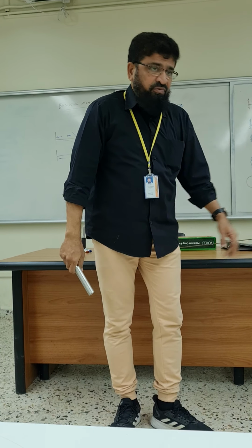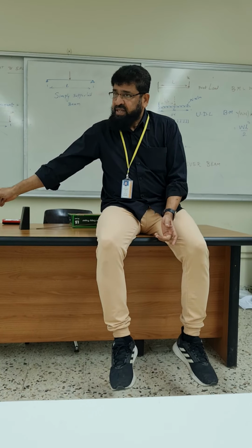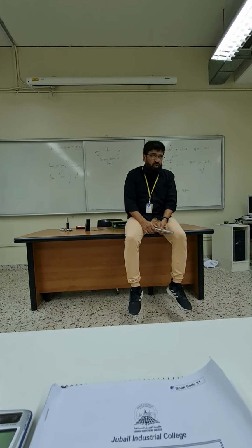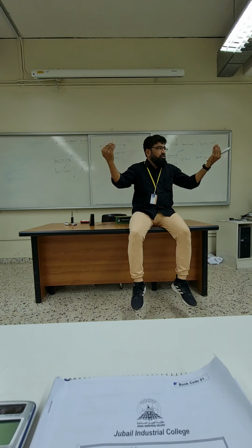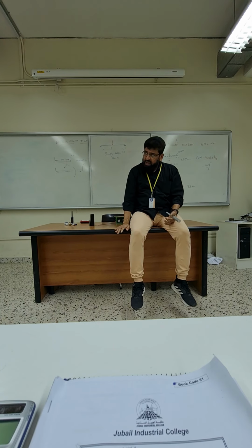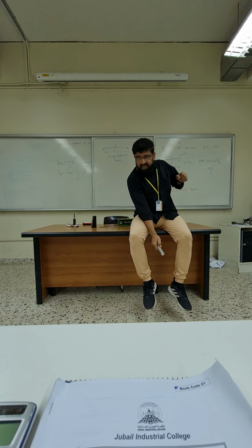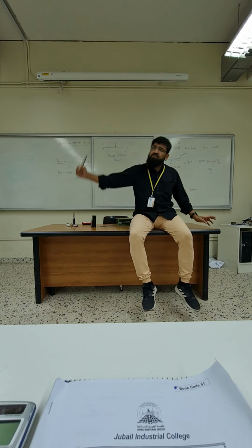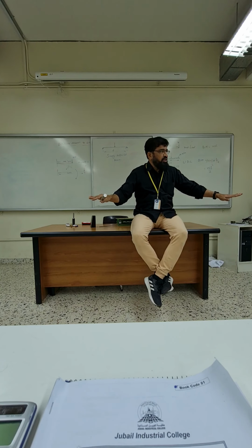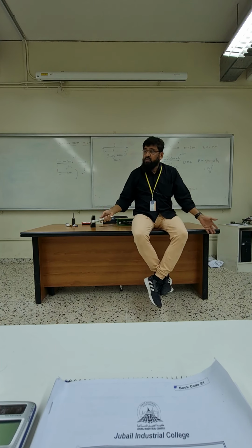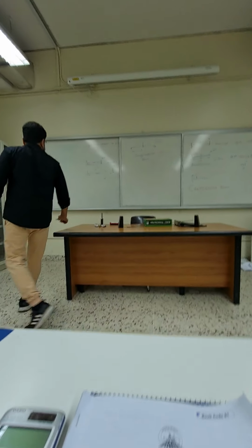So when we want to find out the forces, if I sit exactly here, my weight is 75 kilos. How much does it take? How much does it take? This I have to calculate first. To calculate this, I have to first find out force equilibrium, that is downward force should be equal to upward forces. And then, because of this, what is happening? There is some bending on this one, is it not? I am sitting here, my force is trying to bend like this, isn't it? And there is a support which is like this. This is trying to push it up like this. This and this, they should balance. Then only the beam is horizontal. So with these two equations, we will find out what are the forces there. This is one part of the problem. But what did we write on top here? We wrote two things.